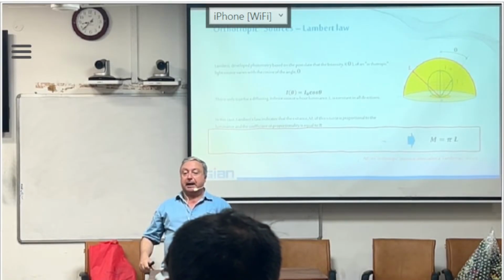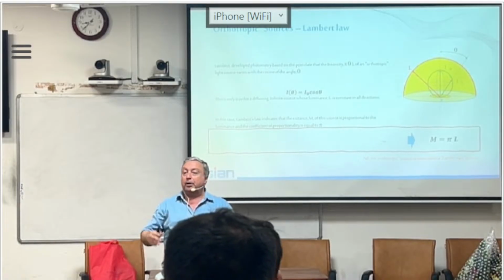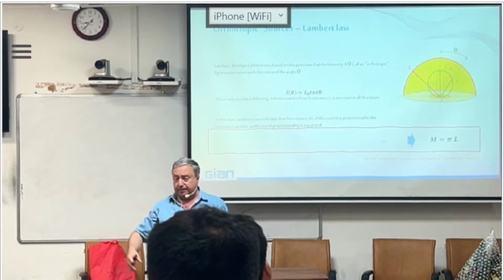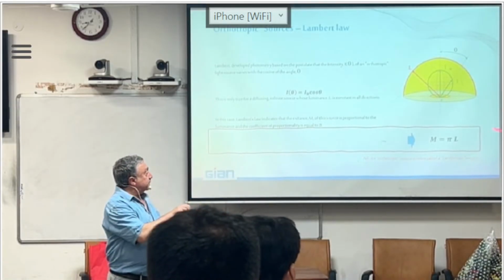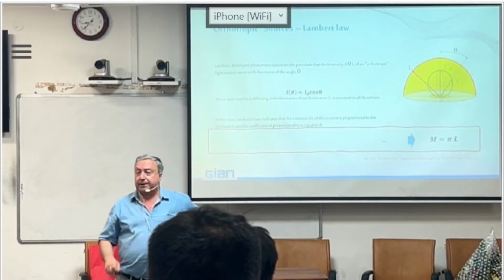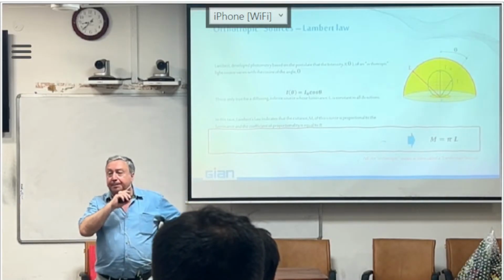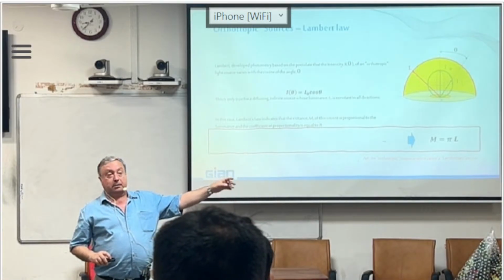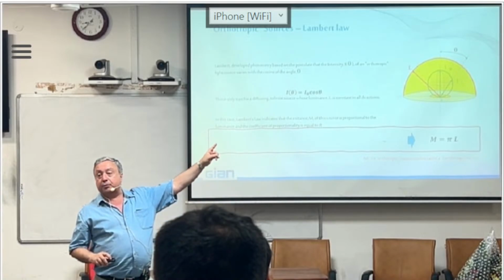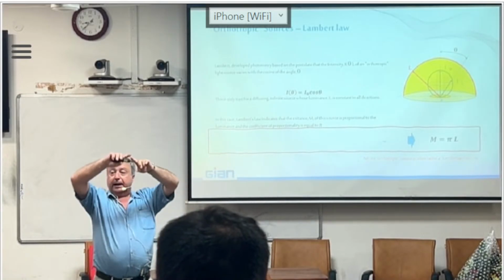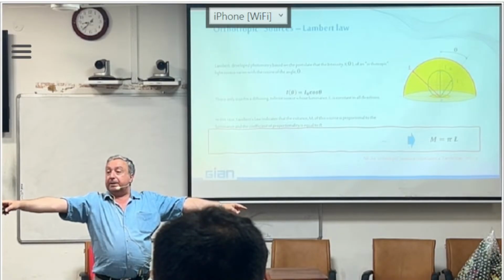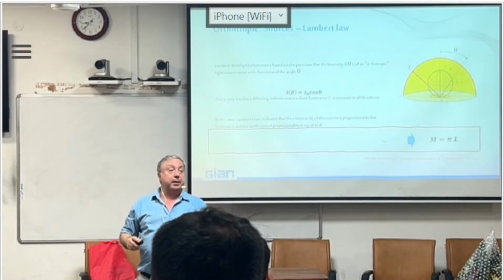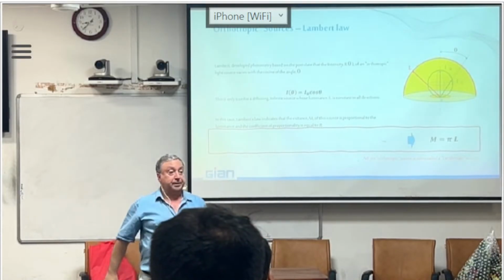If you have this kind of surface, usually a non-reflecting surface, like walls, a piece of paper, the sky, then if you measure the luminance L of the surface, the emittance of the surface is pi times L. If I take a luminance meter and measure the luminance of the sky, then I can find the emittance of the full sky in lumens per square meter of sky.